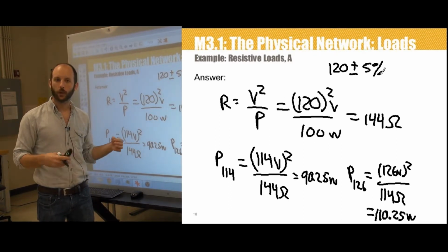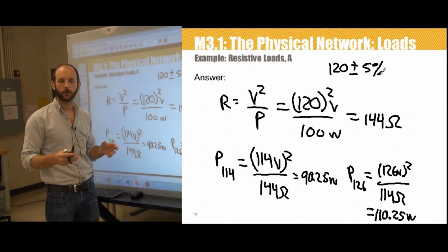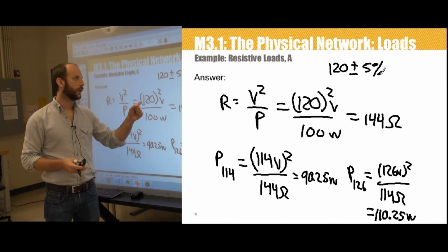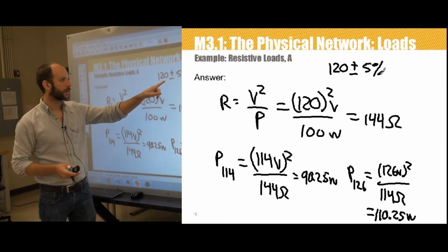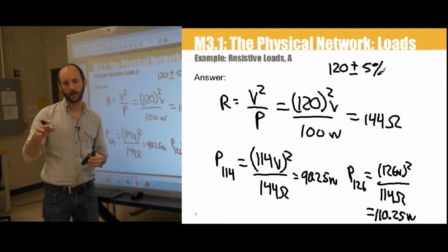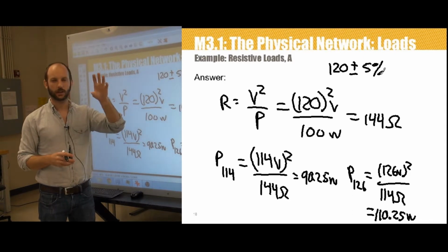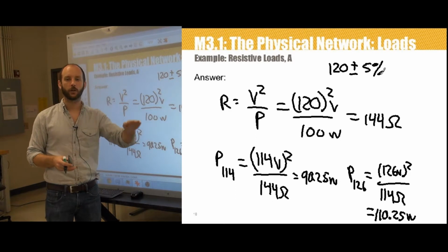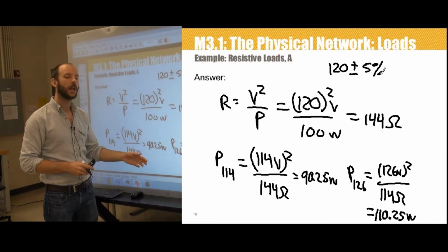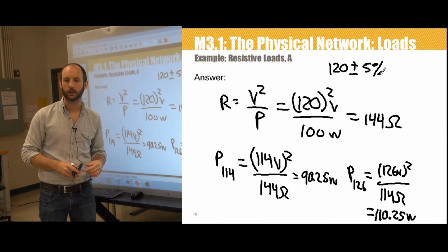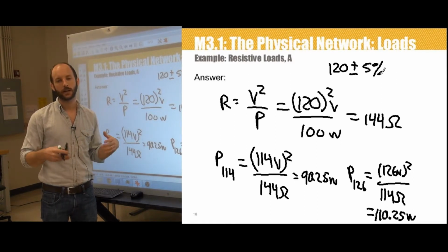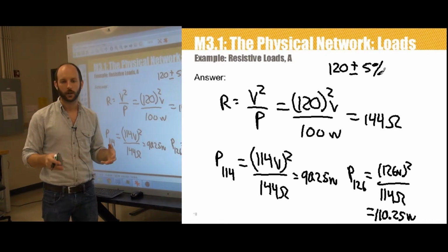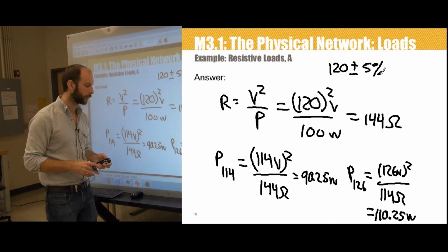Physically, the utility is going out to those load tap changers and reducing the voltage down to the operational limit that gets you to about 114. They're a little bit higher, usually about 116, to account for voltage fluctuations due to transients on the system, but they're intentionally operating you at that lower voltage level as a power conservation technique. That's one of the ideas making up the concept of what we would call the smart grid, new technologies that are influencing the way that the power system operates.